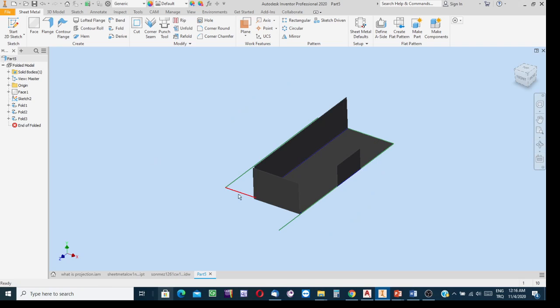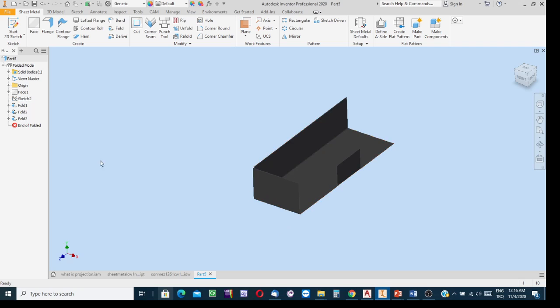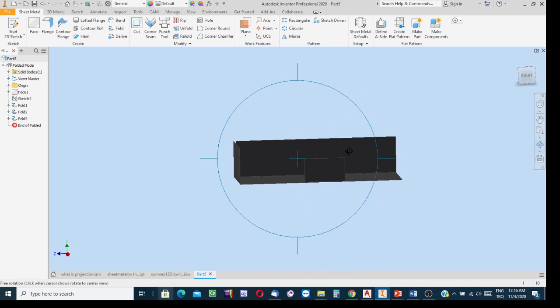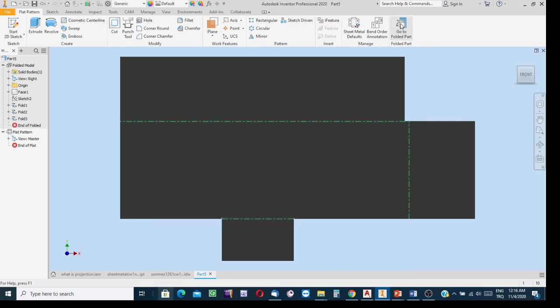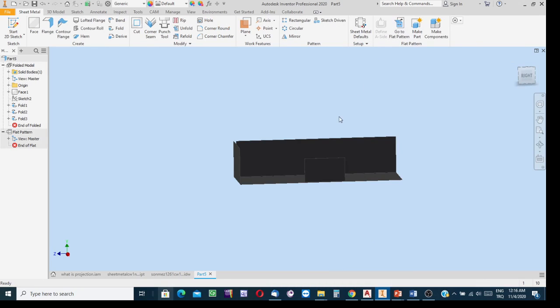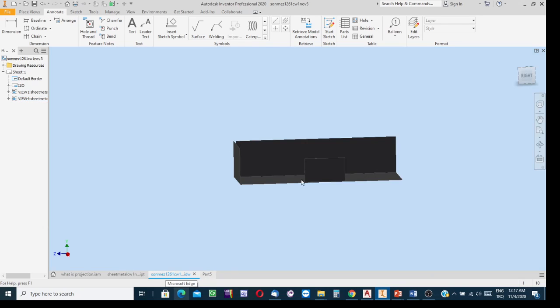Well, if you have such sketch lines on the screen, then bring the cursor onto the sketch icon, right click and deselect its visibility. Yes, and then see the flattened form. Here it is, and then the rest is the same. Create the technical drawing, etc.